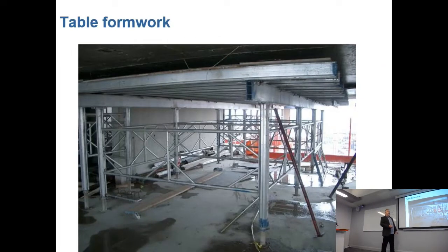In terms of formwork, you can have timber. It's expensive to use joiners, so you have plastics, aluminium, steel, lots of different types. The lighter it is, the less weight is going to be on the building while it's being constructed.